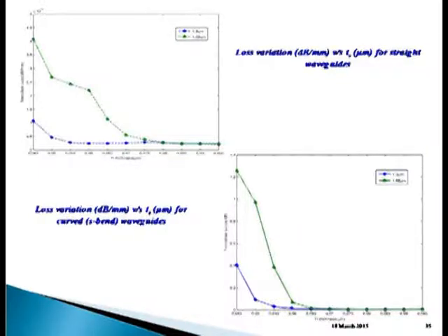And the different thing they came up with was the calculation of the power imbalance of the first stage 3 dB couplers. See, in an MZI structure, this 3 dB coupler is used as a power divider, or power splitter, which splits the power into two equal parts. But when these two equal powers, that is P1, propagate through the interferometric arms, at these two points they become Q1 and Q2 because of some losses.